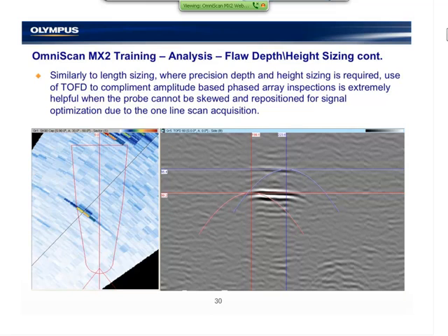And again, TOFD benefits depth and height sizing, particularly on long sound paths. In this sector scan example you see here, it's about a 100 millimeter thick vessel. We're skipping off the bottom and on the second leg coming back through the volume. The farther each angle changes, the larger the gap between two A scans or focal laws. So we could have a 3, 4, 5 millimeter gap between two focal laws, even at a 0.5 or 1 degree resolution.